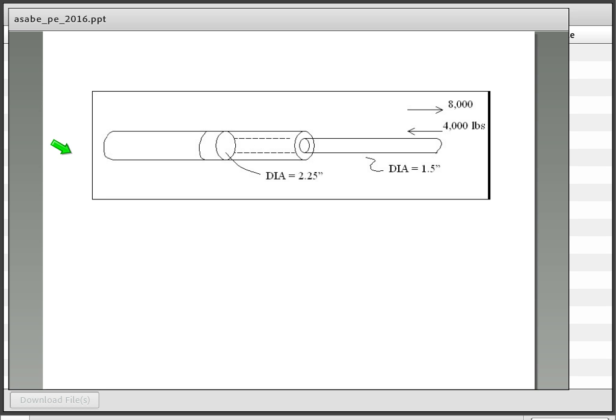You've got a cross-sectional area on the push side of the piston, which is greater than the cross-sectional area on the retraction side. Excuse me, because over here, the effective area of the cylinder would have to subtract out the cross-sectional area of the rod itself.